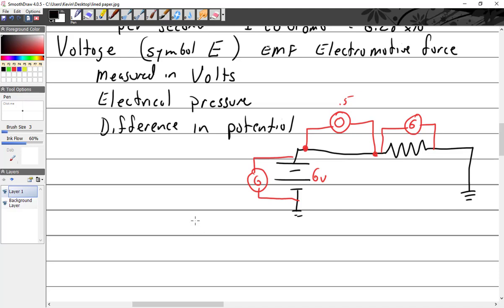That voltmeter won't read 6, right? Against the resistance in the series. Right, this one right here won't read 6. This one will. It'll read 6 because there's only one resistor. If I add another resistor, that's going to change. It won't be 6 anymore. It'll be something else, depending on what the resistance is.